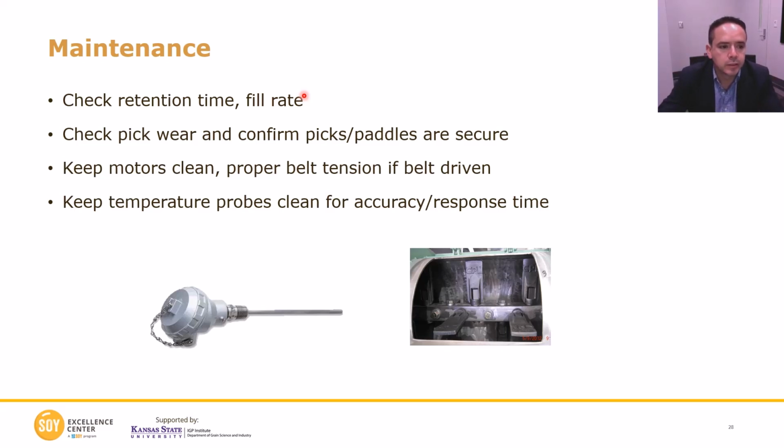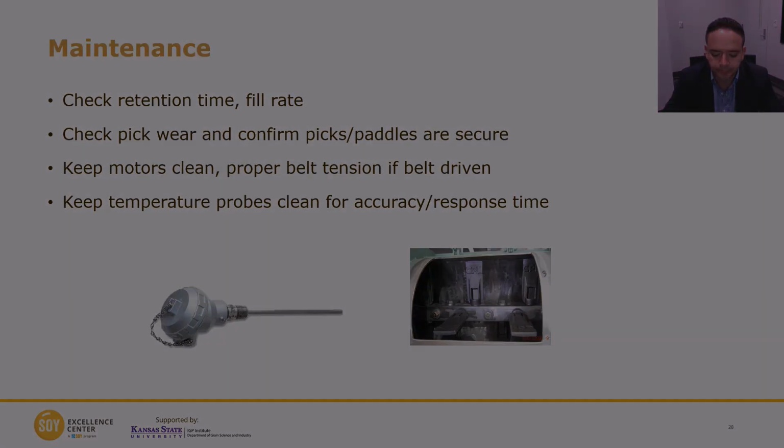Also, you want to check pegs wear and confirm that the paddles are secure, as you can see here in this photo. Also, you want to keep the motors clean, make sure that the belts have the proper tension, and also make sure that the temperature probes are clean, because if they have some buildup, then they are not going to be able to record the temperature correctly.